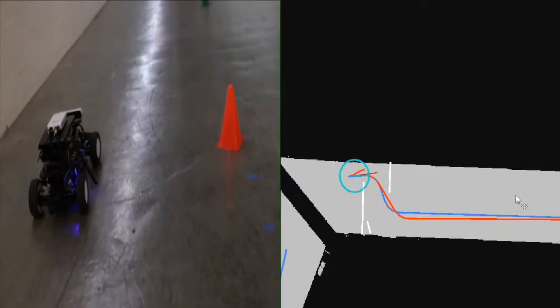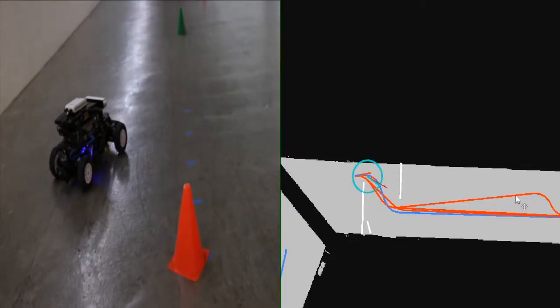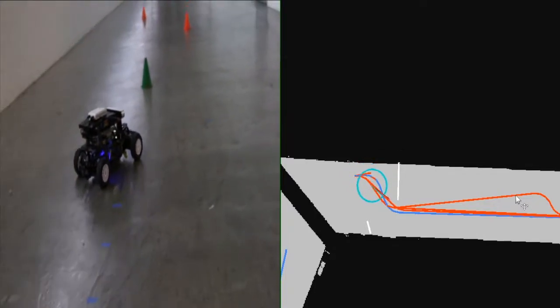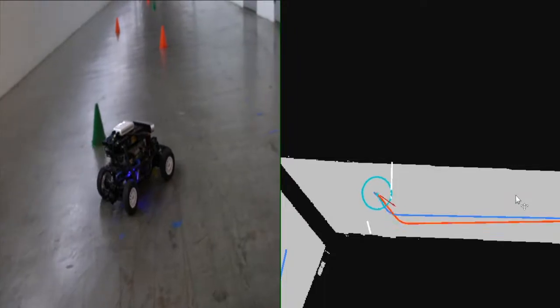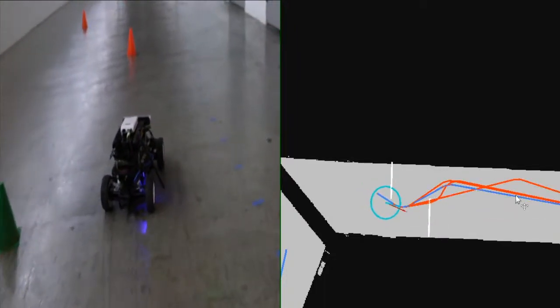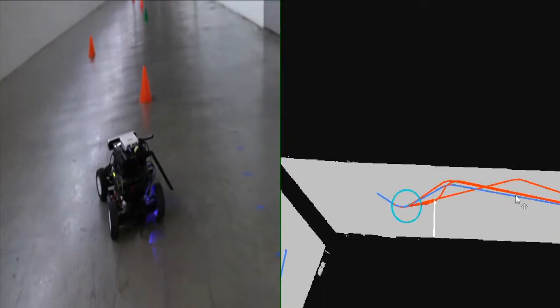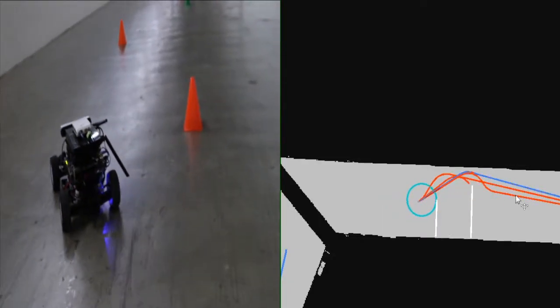This is what the robot sees while driving. The color threshold filters out anything that isn't an orange or green cone. A bounding box is drawn around the remaining parts of the image that also meet cone area and aspect ratio criteria. When the robot perceives a cone, it plans an avoidance path by sampling points to one side and iterating through possible trajectories. It then chooses the best path, as seen in blue, to correctly drive around the cone.